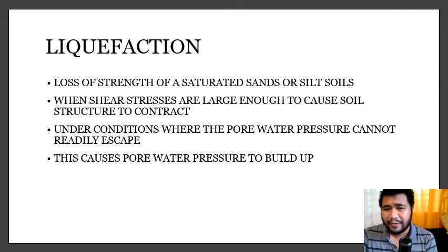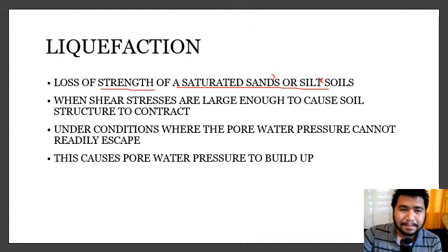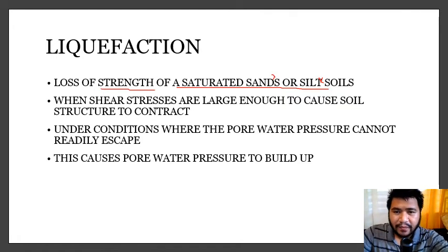Now let's talk about liquefaction. Basically, it's a loss of strength, a loss of effective stress, in your saturated sands or sandy or silty soils. This happens when the shear stresses are large enough to cause your soil to contract.